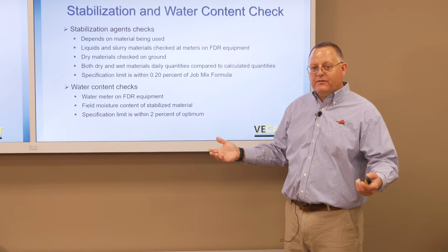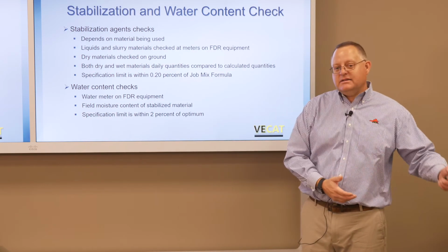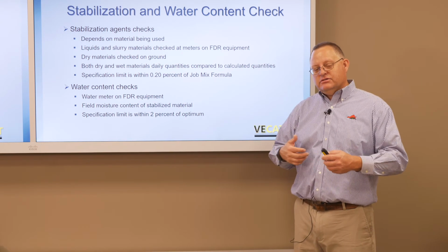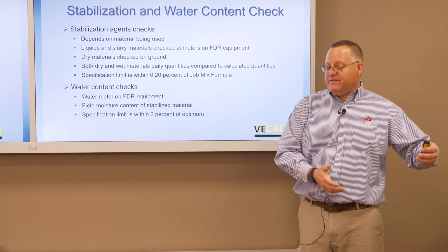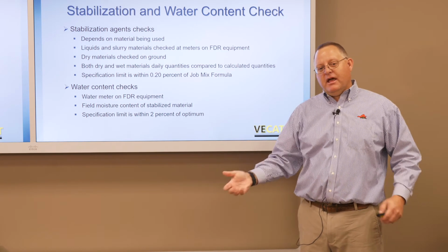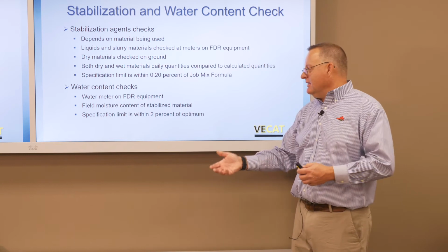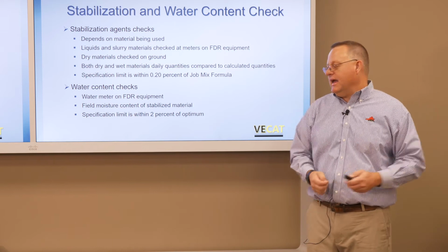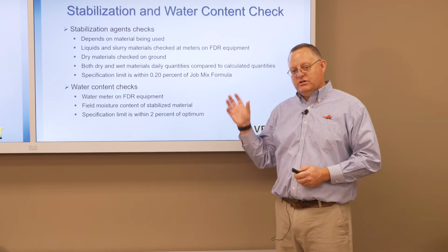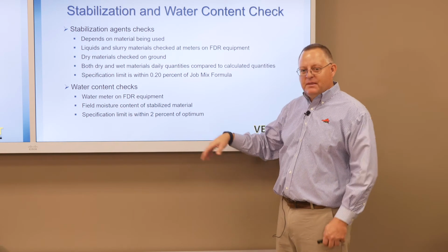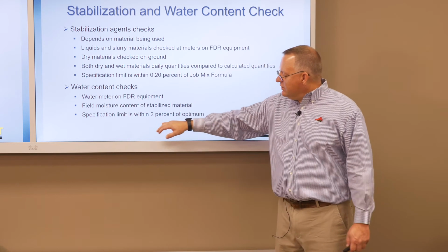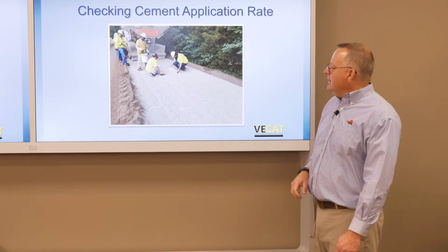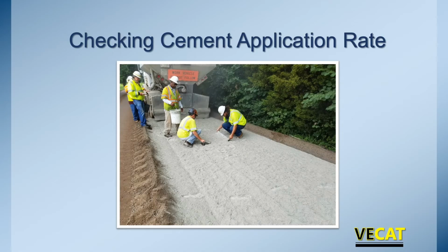Again, you're not going to be perfect because if you think about it, the moisture content of the material in the road itself varies along the length. So even if you've set it up at 5%, depending on how much of that moisture changes within that existing pavement, you're not varying it every few feet as the actual moisture content in the road changes. So you're setting it, you're applying it based on that moisture content, and now you're just making sure you're within 2%.